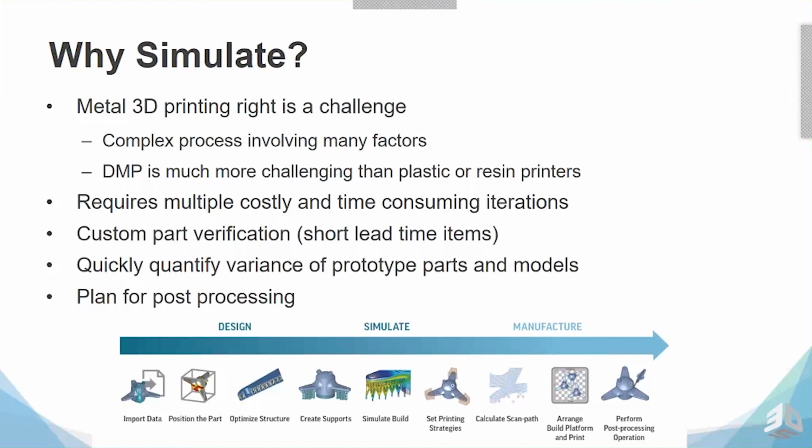If you have custom parts that are short lead time and maybe a little different than the ones that came before it, so custom medical implants, we're just talking things that aren't serial production, you have to do those supporting and pre-processing activities every time, and it can be really time-consuming, and it can cause you a lot of problems if the build fails.